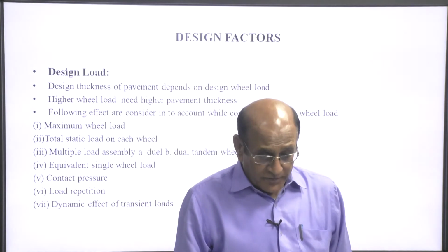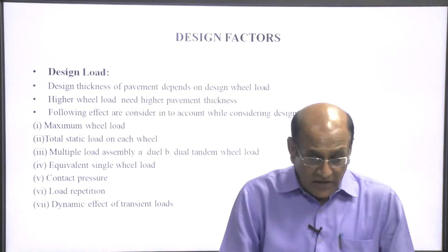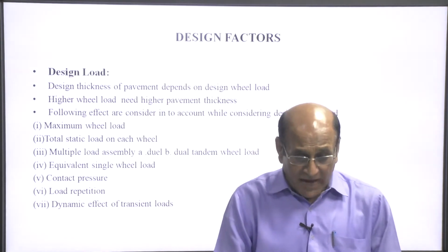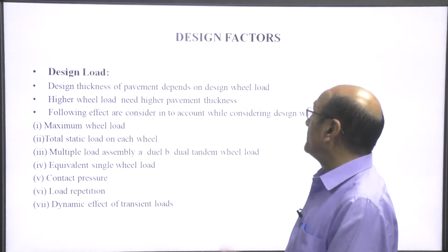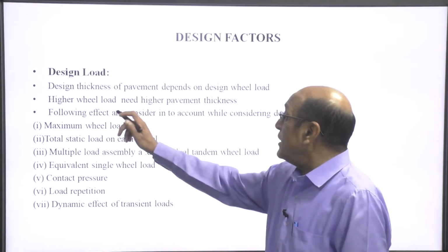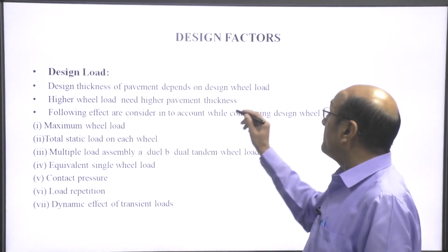Now, design load. Design thickness of the pavement depends upon the design wheel load. Higher wheel load needs higher pavement thickness.